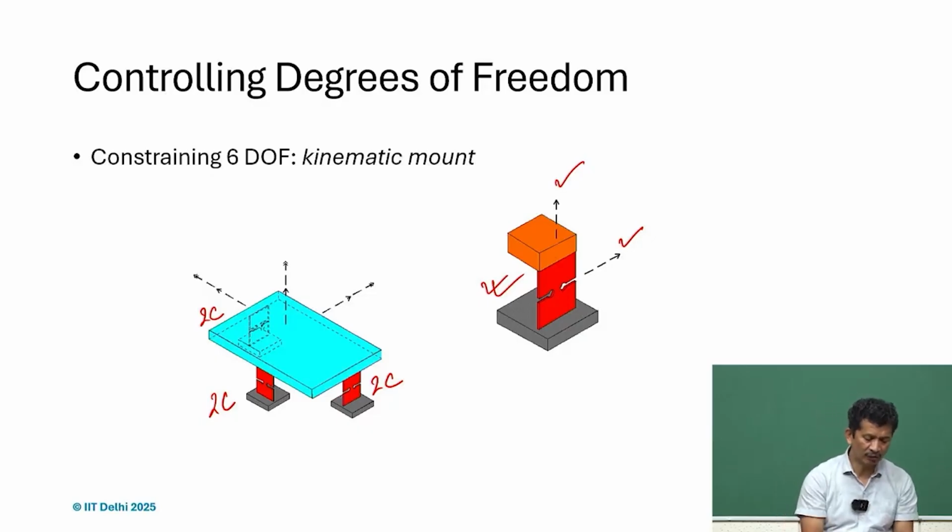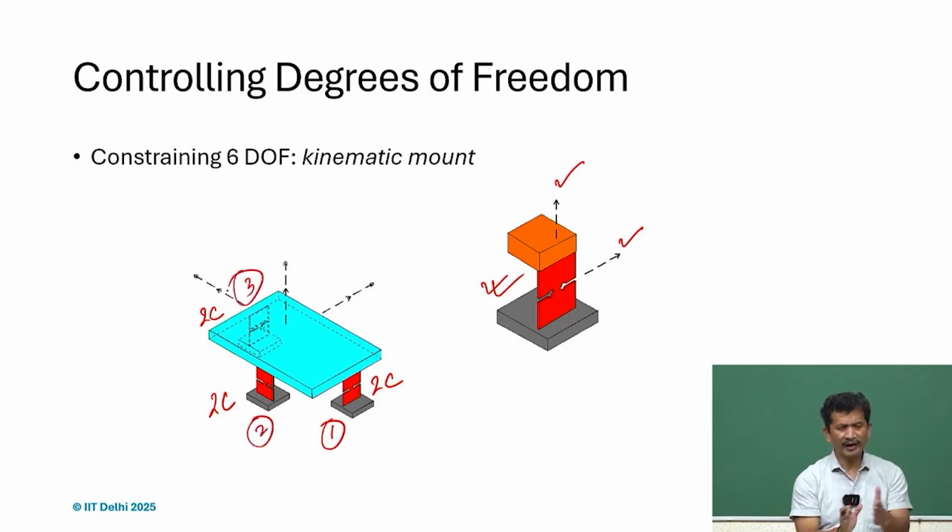Of course, the orientation matters. If I call them elements 1, 2 and 3, 1 and 3 are parallel, but element 2 is not in the same plane. If it is in the same plane, what will happen is over constraint, because if you try to move, all will flex, all will bend, and then it will not restrict that motion. So, it is then an over constraint design.